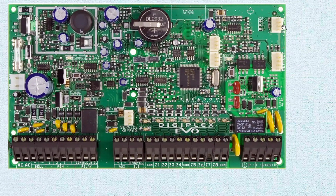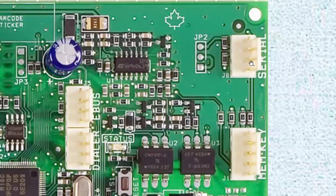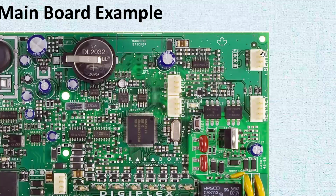Quickly before I let you go, here's a serial interface port in this particular one. Some other ones may have it in a different spot, but through the serial interface port, you buy a physical jig from the same company that sells the alarm. It's a serial interface. You plug that into the USB of your laptop, and the other part is plugged in here, and that's how you establish the communication between your laptop and this security alarm. And that's when you can do the programming through the software that you have to install on your laptop.